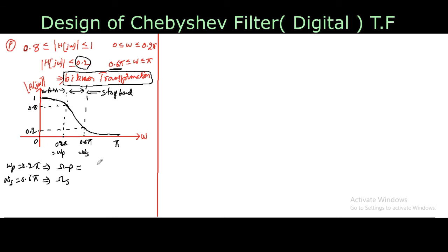So before defining the transfer function, write the relation between analog frequency and digital frequency using one standard mathematical equation. That equation comes under pre-warping. Here, Omega = 2/T tan(w/2). Now I want the analog passband frequency, that's why I am taking wp/2. This is the pre-warping mathematical equation.